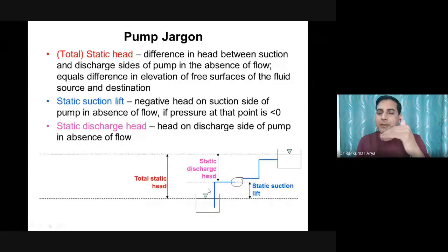After that, we have to design the location of the pump to be either equal to that or slightly lesser, to be on the safer side. So this condition fixes where I should fit the pump above the liquid level. Correct?